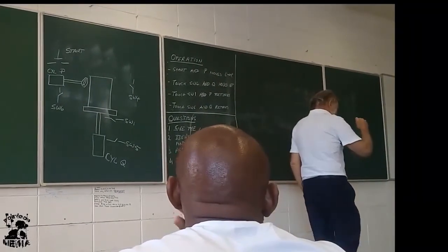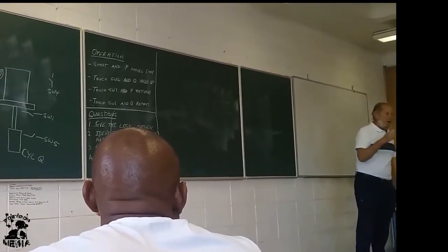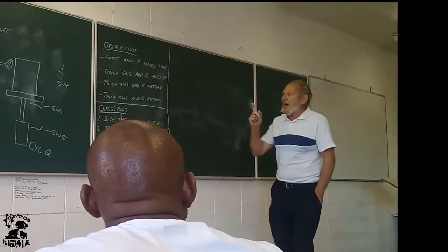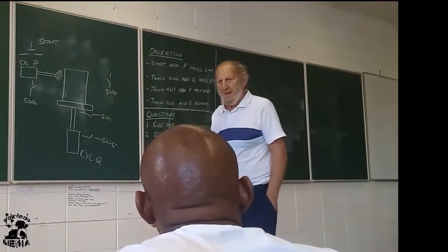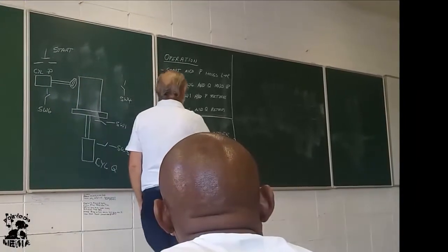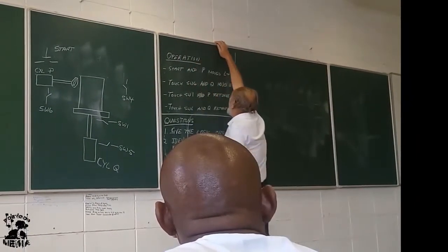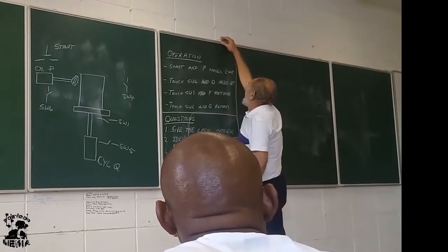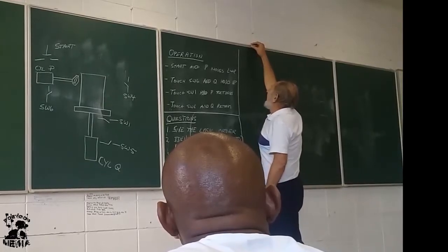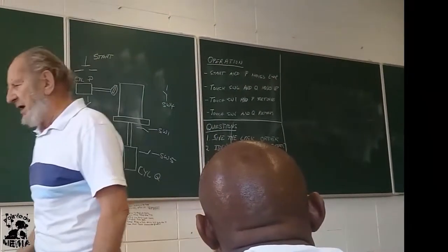Right. Firstly, before you start, check the drawing. And on the drawing, mark which switches are closed in the beginning.